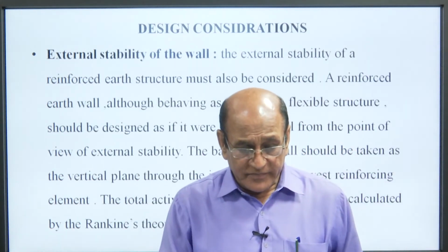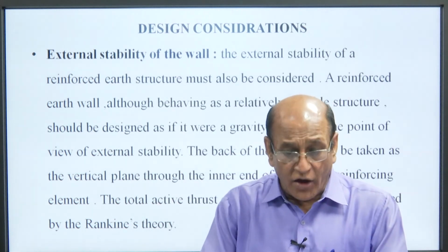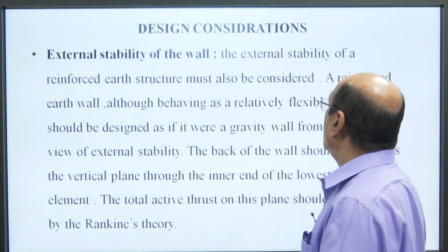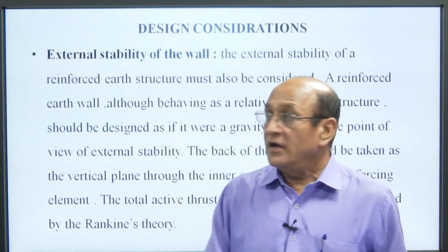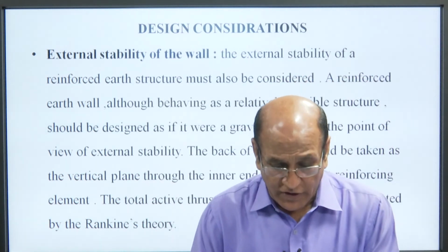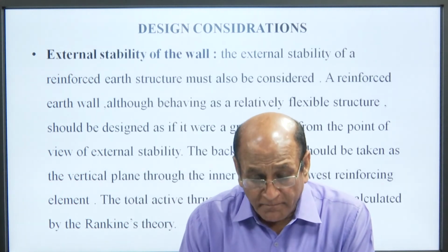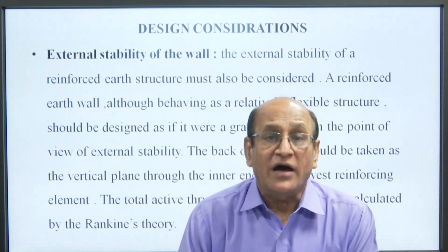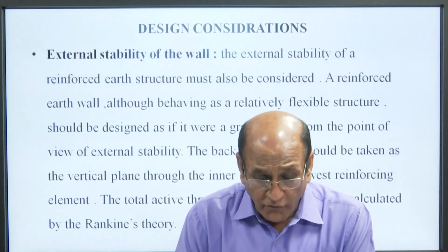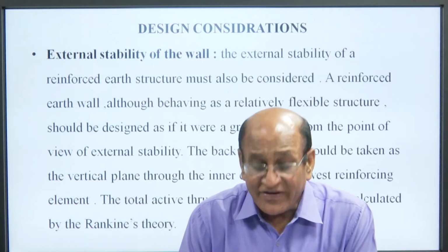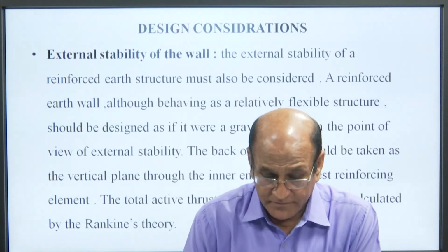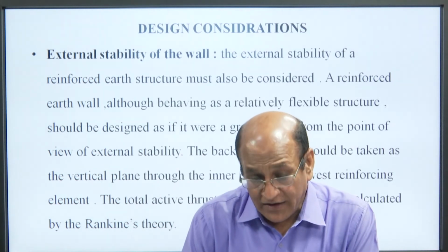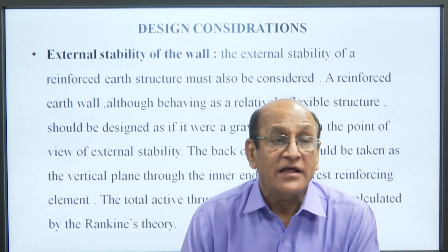Now, come to the external stability of the wall. The external stability of a wall of a reinforced earth structure must also be considered. A reinforced earth wall, although behaving as a relatively flexible structure, should be designed as if it were a gravity wall from the point of view of external stability.